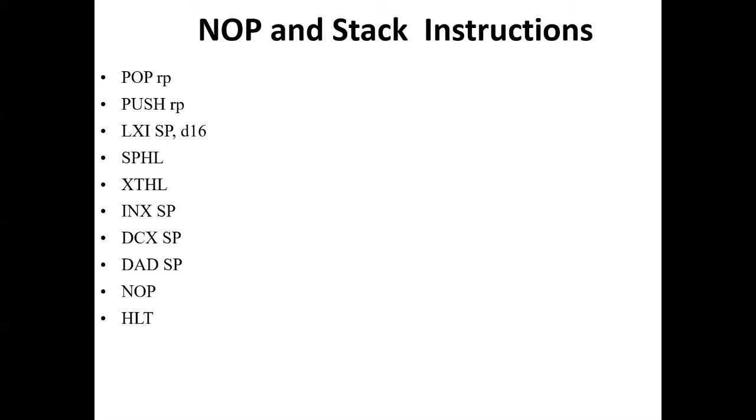Next is DAD SP. DAD SP instruction is a special case of DAD RP. DAD SP instruction is used to add SP contents to HL contents and store the result in HL register pair. It occupies only 1 byte in memory.